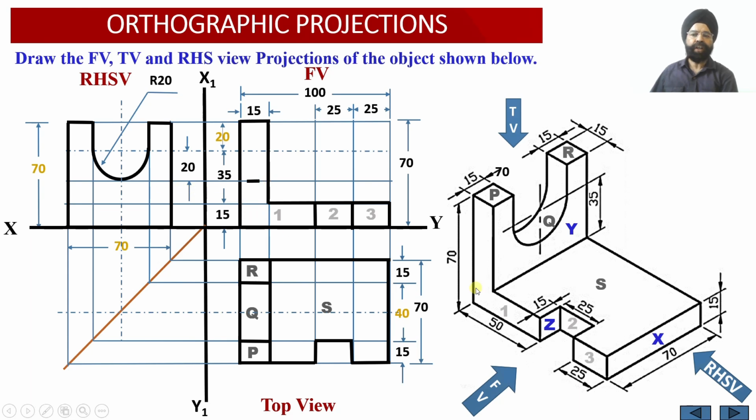Now let us draw this portion of the side view. So in the side view, surface X, it is visible to the observer. So I can draw the surface X over here. So the complete surface happens to be surface X, whereas there is another surface Z which lies behind the surface X over here. So this is surface Z which will be overshadowed or covered by surface X.